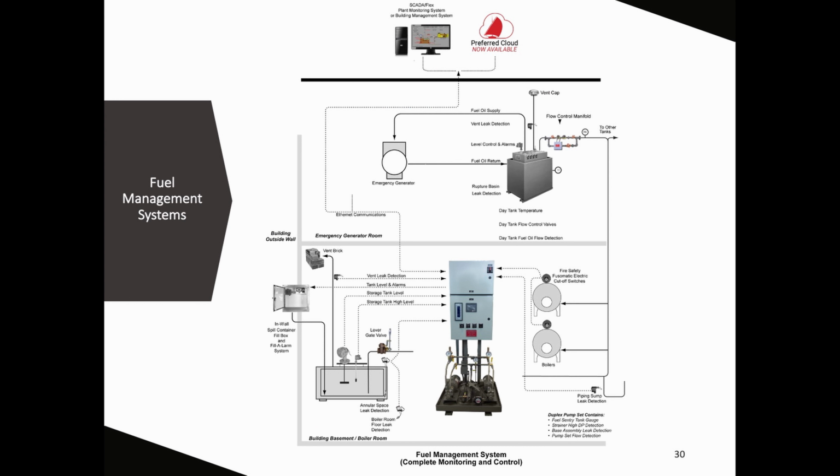So here we have a typical fuel oil system for a generator on a different floor. You got your fill, your tank, and then you got your emergency generator up on the roof with a day tank nearby it. These pump sets can be as simple as a hand-off auto switch on the pump set, or it can be as complicated as a PLC system.